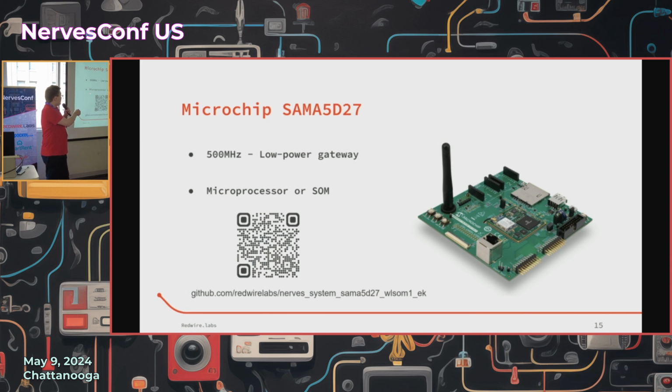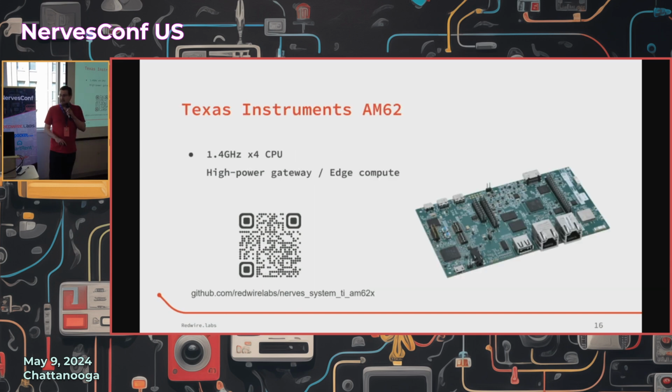The economical difference of why you'd want to be looking at this too is the SOM is going to give you a higher BOM cost. So it's more to buy that section there. But because it's got more stuff on it, it costs less in design time and NRE cost to engineer that. If you need to scale up into higher volumes, get the microprocessor because that's cheaper on the BOM, but you'll have to spend a little more time integrating all the other components into the system. So that's one good place to start.